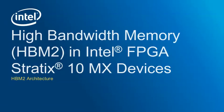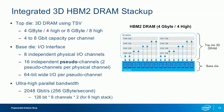Now let's look at the basic HBM2 architecture and how it is implemented in Intel Stratix 10 MX devices. As already mentioned, HBM2 is three-dimensional DRAM technology consisting of a stack of silicon dies. The top die consists of the main stack of DRAM, while the base die includes the I/O connections to the host device. The top die includes either 4 or 8 individual DRAM dies that are connected together using TSVs. The 4-high version has 4 GB of capacity, while the 8-high version is 8 GB. Each die in the stack consists of 2 physical channels. These channels are duplicated in the 8-high stack.